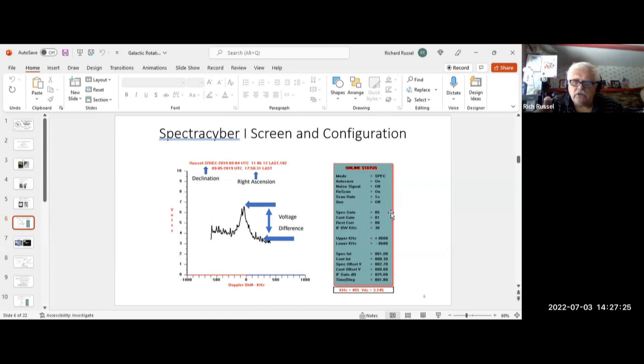The one thing that I would change on this, and I've done it once, but I couldn't find my signal generator, is to get a signal generator that you can set for the exact center frequency, turn it on in front of this thing, and calibrate your 0 point.